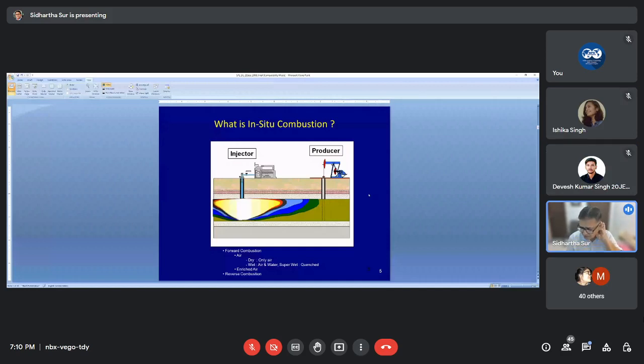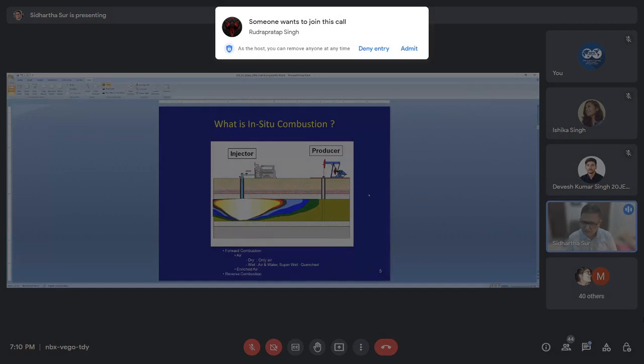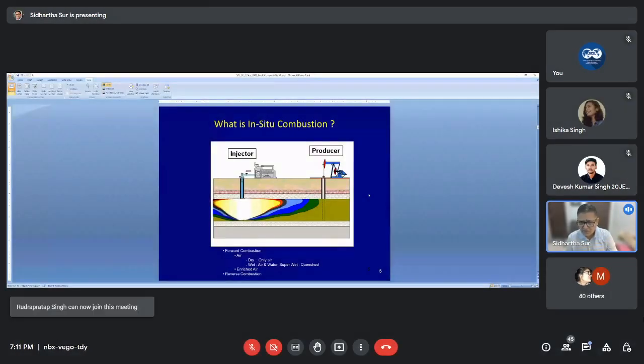Here it's all thermal cracking because the high temperature of that red front heats up the oil ahead of it in an inert atmosphere. All the oxygen in the air is getting consumed at that red portion. So in the zone ahead, nitrogen makes a free trip across the reservoir. It's inert, it doesn't go into any reaction. Oxygen is getting consumed in the red portion, which is the front. So the oil ahead gets heated up gradually, with rising temperature, and it gets cracked.